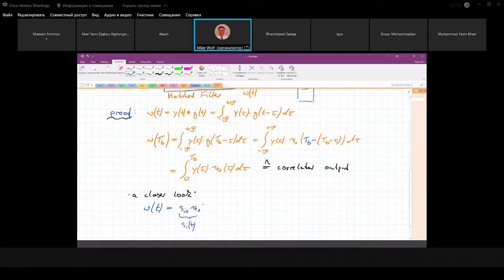As you can see, this s of t is just our basis function, but with a weighting square root of E_b, nothing else, then plus the noise n of t. Then we do the convolution, because our impulse response is just psi1 of T_b minus t. It's exactly the same. So what do we get? We do this convolution of psi1 of t with psi1 of minus t.